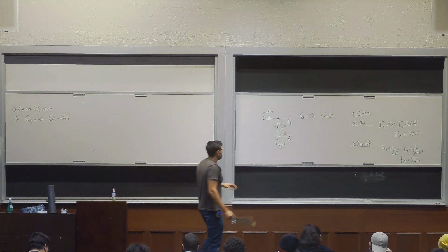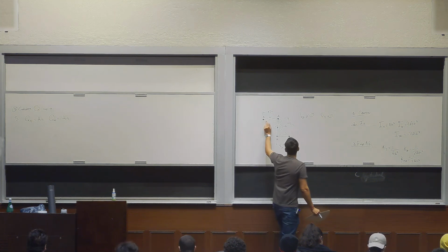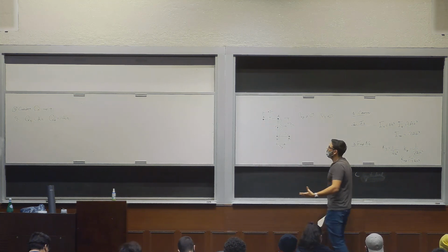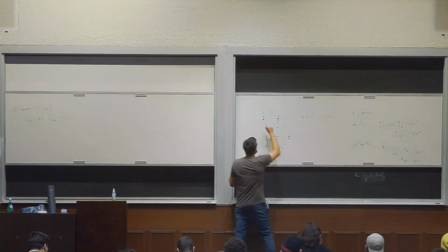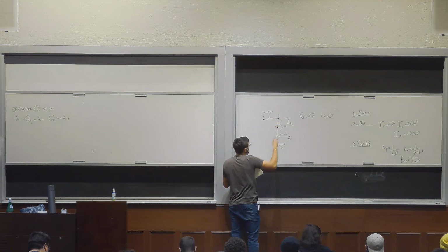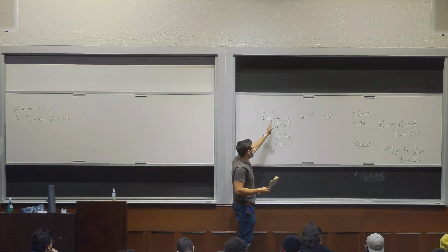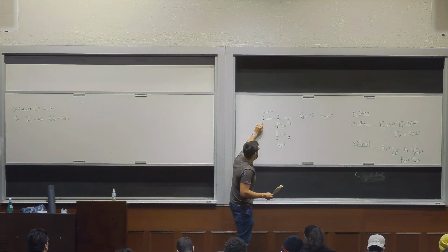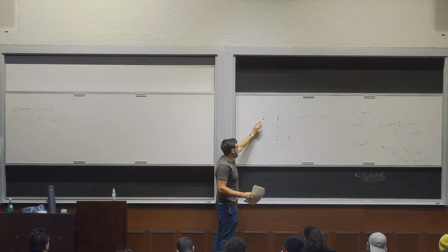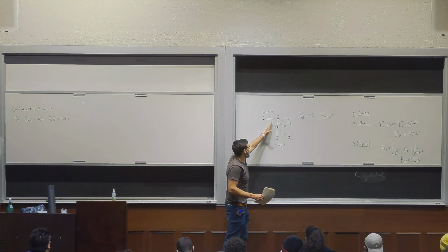Okay, so the important thing here is to remember that these webs don't add any area. In the previous examples, these had some non-negligible thickness, so the area would keep increasing as you move down S1. In these problems, this web has a negligible area, so the only area that matters is the area with which you start. So in this case it's A, and it's going to be A throughout this whole length.